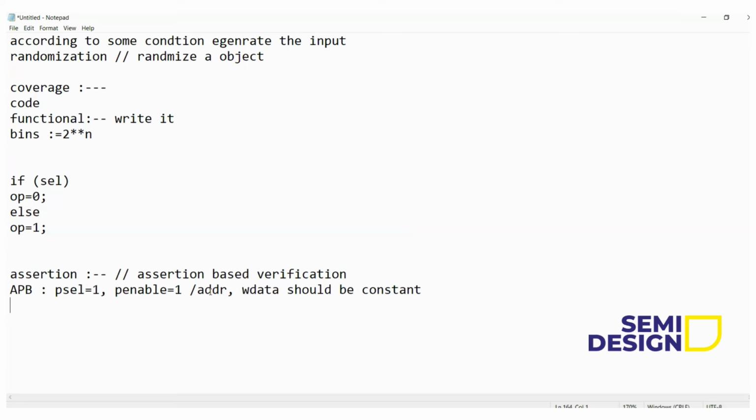So you can say that your verification is completed when, first, you get the correct, desired output through your reference model or scoreboard. If I'm doing an adder, I should get the addition result. Next, I should get proper coverage, whether code coverage or functional coverage, approximately 100% depending on my requirements. Third, assertion: I should have no assertion failure. So these things I need to check. Got it. Sure. So this is the total advantage of SystemVerilog.